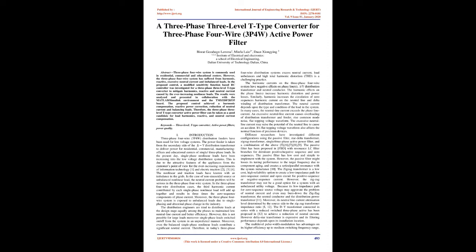Moreover, the 3-phase 4-wire system is exposed to unbalanced loads due to single-phasing and abnormal phase change in industry. Distribution engineers try to distribute loads at the design stage equally among the phases to maintain low neutral line current and better efficiency. However, this is not possible for large loads. Moreover, single-phase loads are switched on/off in the system in an unpredictable manner. Even balanced single-phase nonlinear loads contribute a significant neutral current.